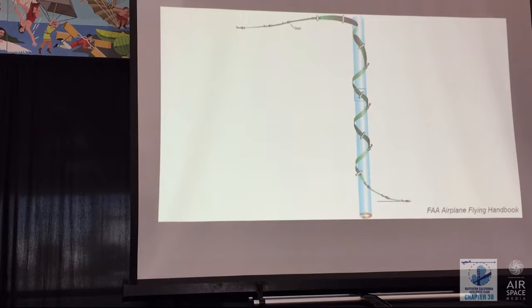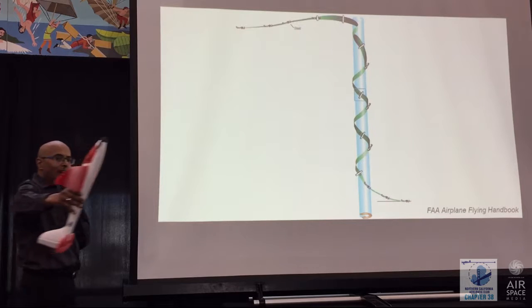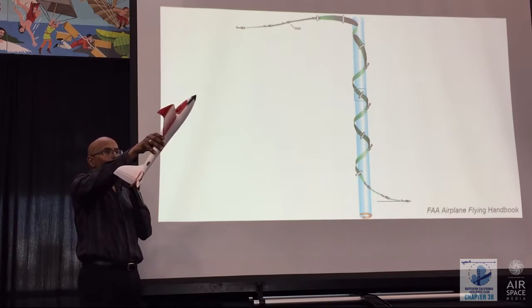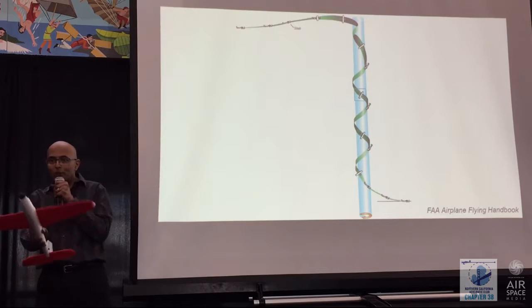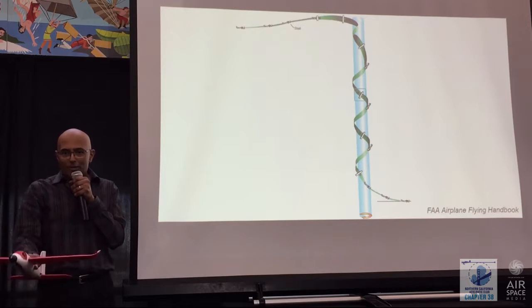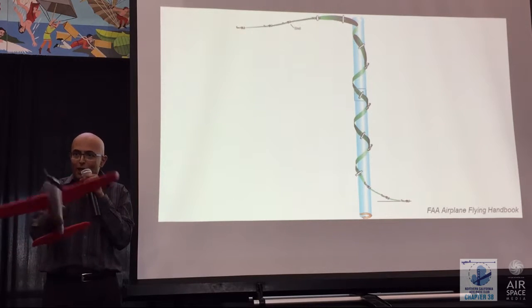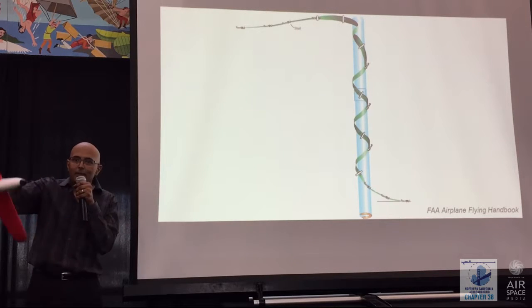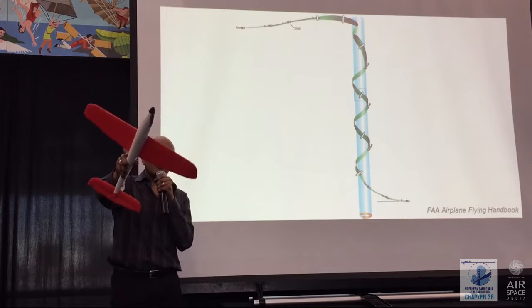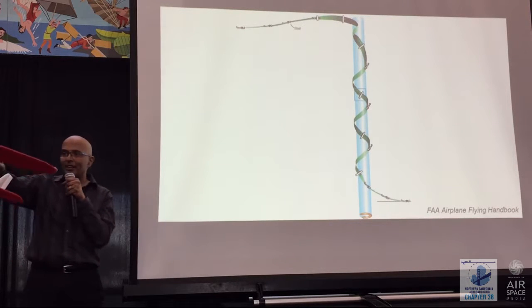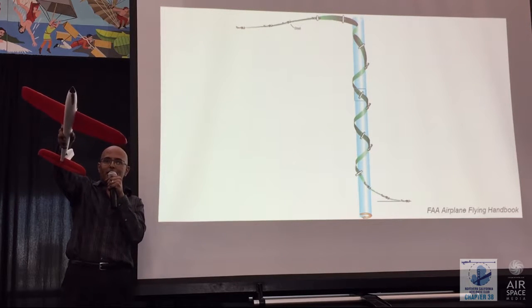The more insidious thing is what happens if you are flying into the air and you stall, but you're not pointed straight at the air. Airplanes are supposed to be symmetrical, but they actually aren't, because the propeller is turning one way rather than the other, and sometimes you're turning. So sometimes you're not pointed straight into the air. And what happens then is that one wing stalls before the other.